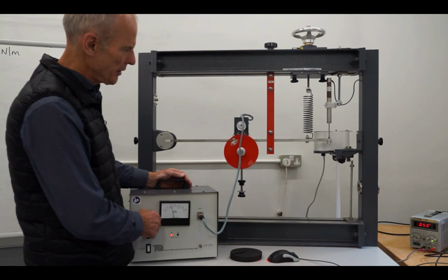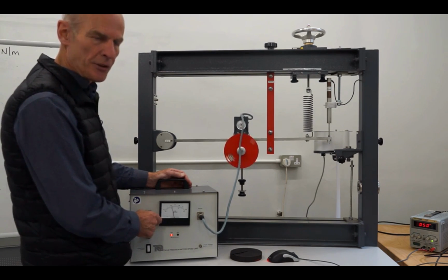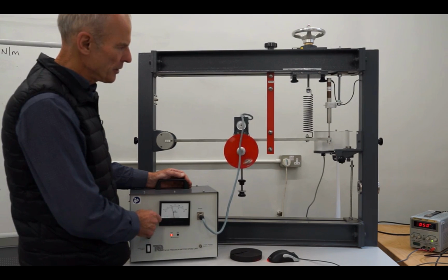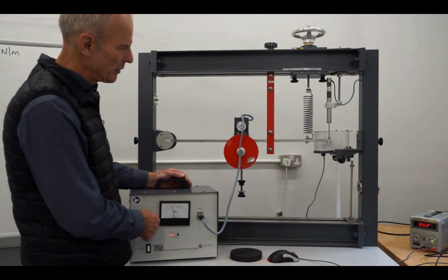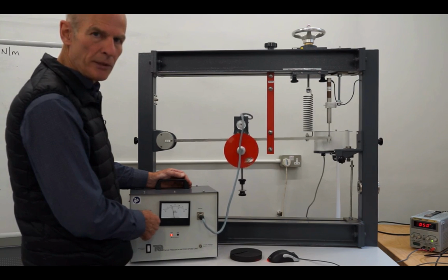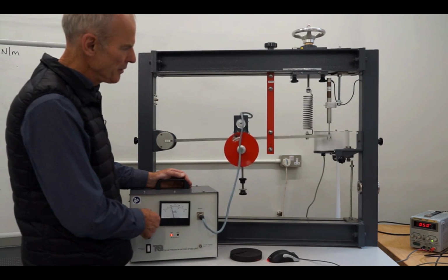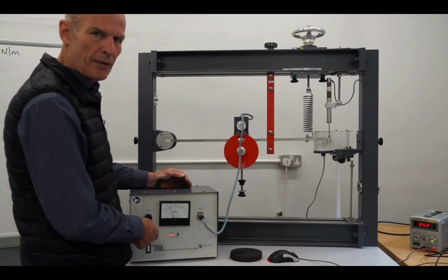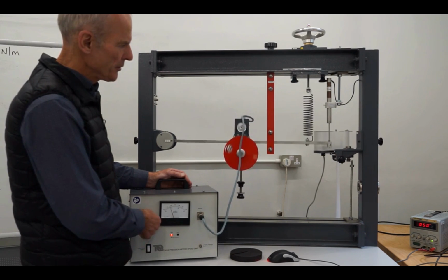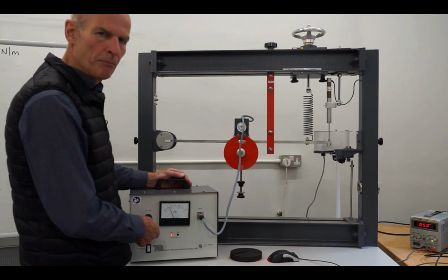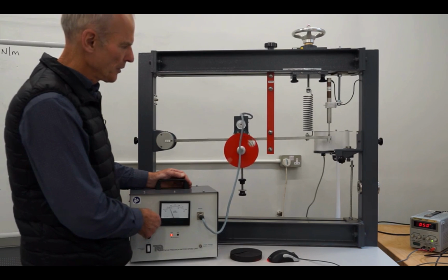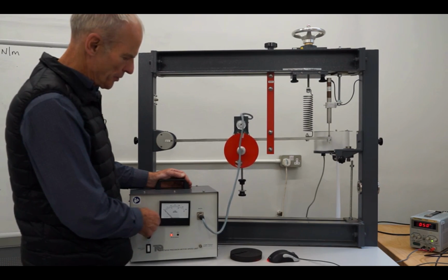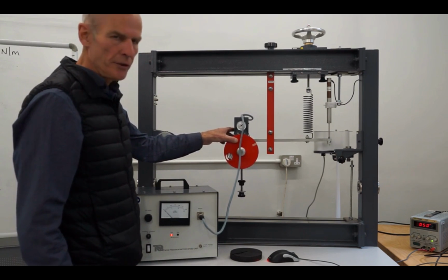If we keep applying this, then at some point we're going to approach the natural frequency, and you can see that we're going to get larger and larger amplitude vibrations. Looking at this, it's rocking up and down quite aggressively, and this is approaching what we call resonance. If you wind it down a little bit, you get some sort of more haphazard response, and you could actually get what we call the beating phenomenon, which we've also discussed in the lectures. Paul will explain that.